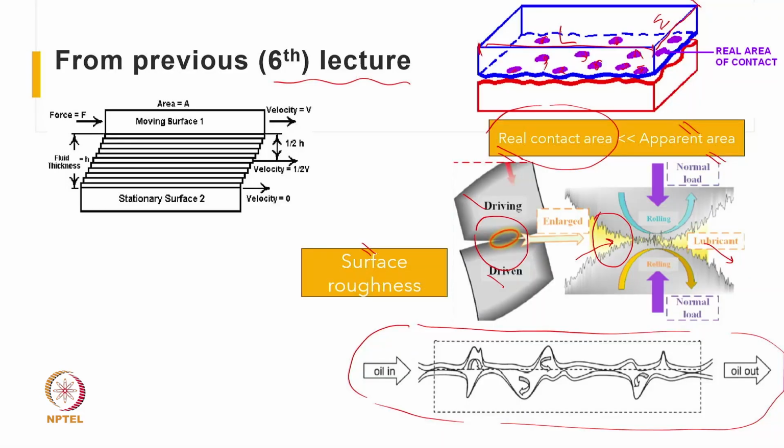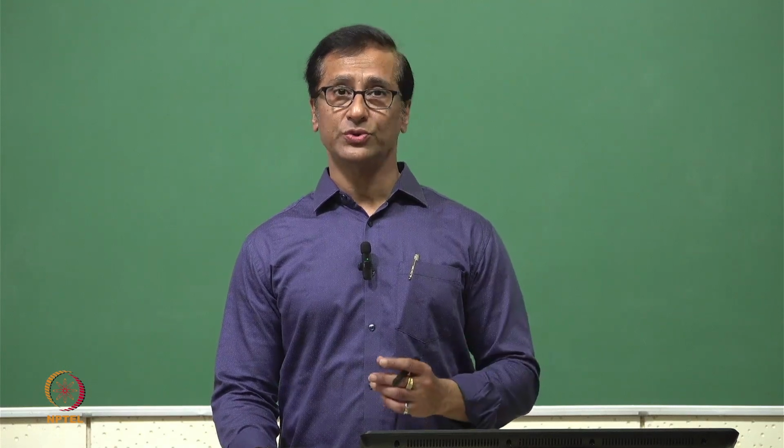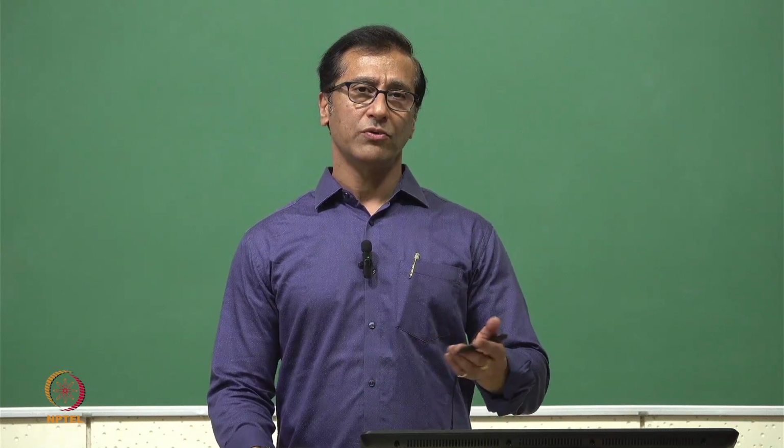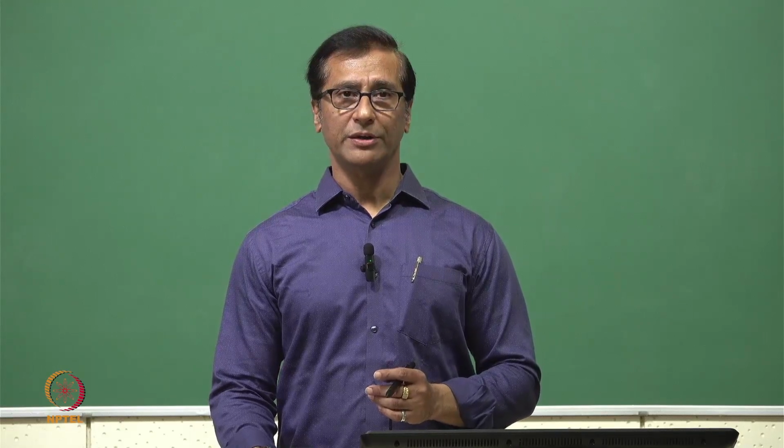Of course, to compare it, we also took the example of thick film lubrication. We say the two surfaces are completely separated, and this is a typical example of hydrodynamic lubrication. That is why we say lubricant, lubrication and lubrication regime need to be understood together. Even though I am using the word hydrodynamic, if the lubricant is air or gas, then it will turn out to be aerodynamic. Of course, the principle remains more or less the same. Equations will change to some extent, and the aerodynamic mechanism will be slightly more involved, slightly more difficult compared to the hydrodynamic.